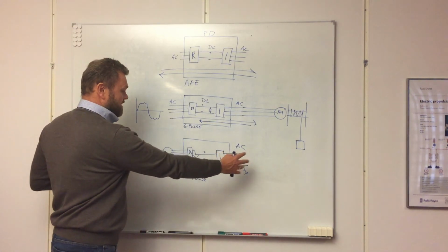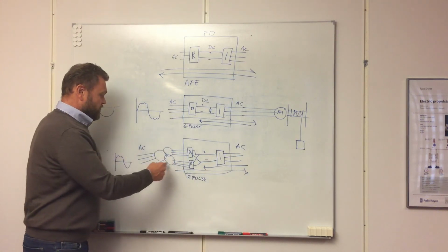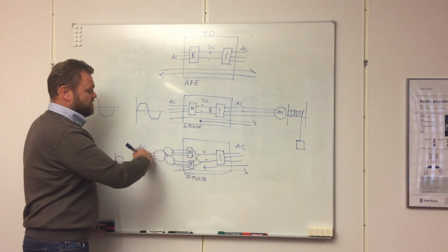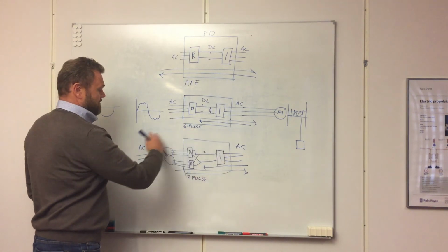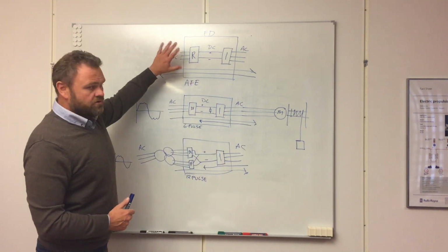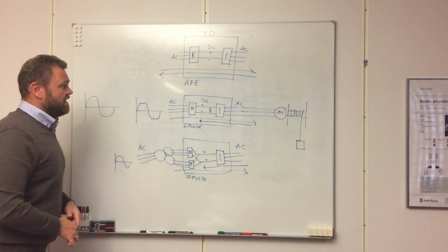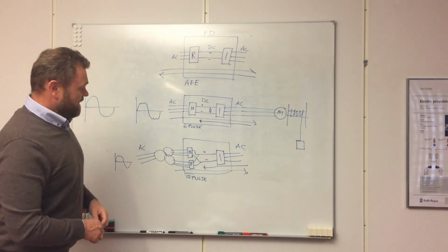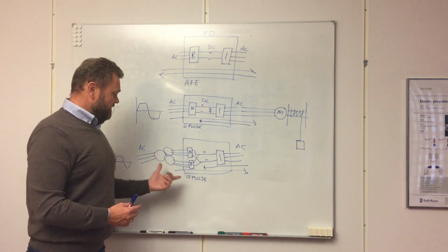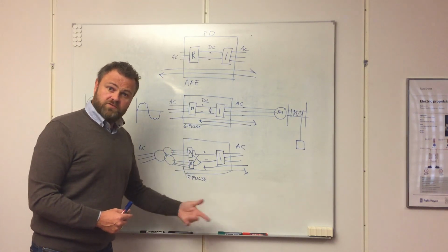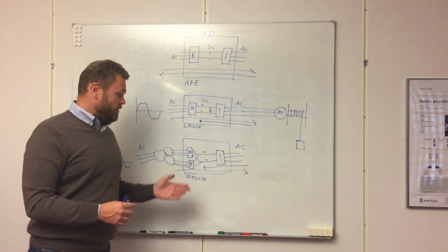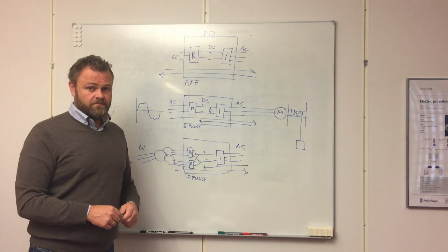However, if you bring in the complete picture with the transformer, the installation, the termination, the cabling, and all those things you need to keep this system in a good way on board a vessel, then you're not far off with the active front end. And given all the other benefits, it's a good frequency drive. Nevertheless, we have these products as well, 18 pulse, 24 pulse, and in some applications it's wise to go in that direction.